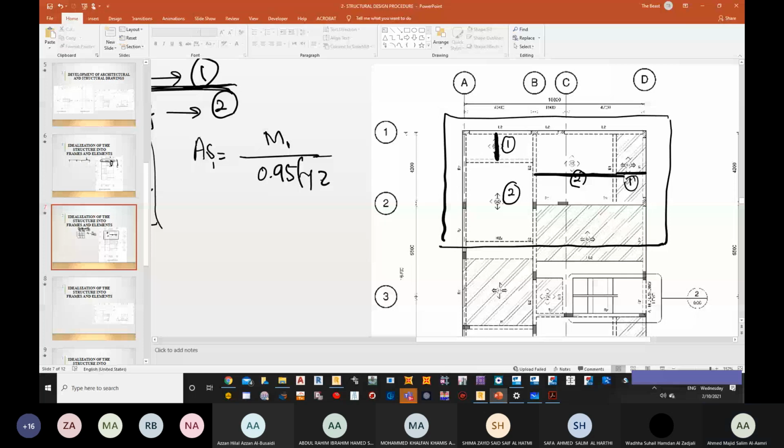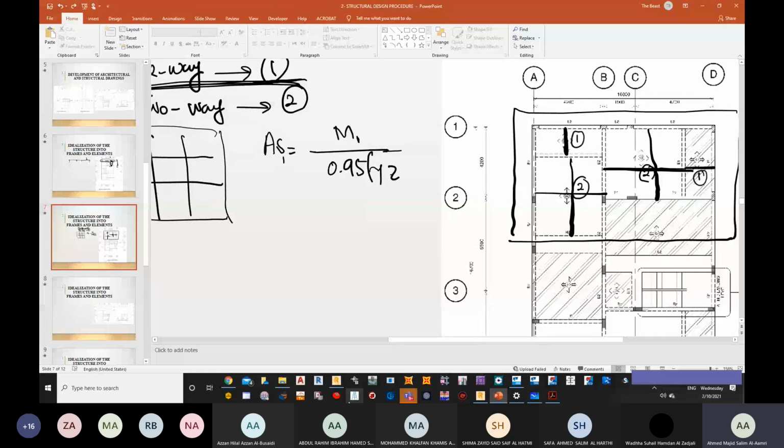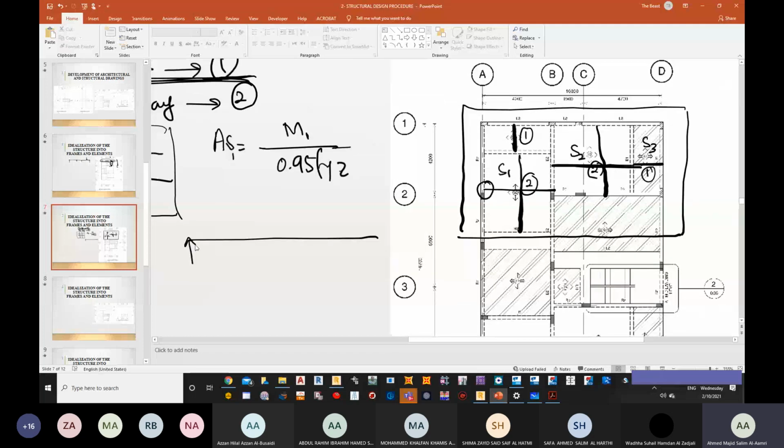here, then I can draw my slab as this, where this is, let's say, slab number 1, this is slab number 2, and this is going to be slab number 3. So slab number 1 is supported by, let's say, a beam here. So I have a beam. Slab is always supported by beam. Beam is supported by either a column or a beam. Okay. Slab number 2, this is the other or second support for slab number 1. Okay. So let's say that this is reaction number 1.